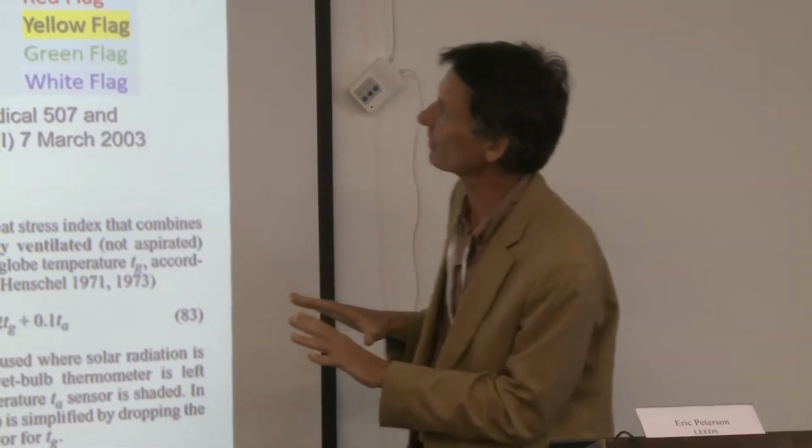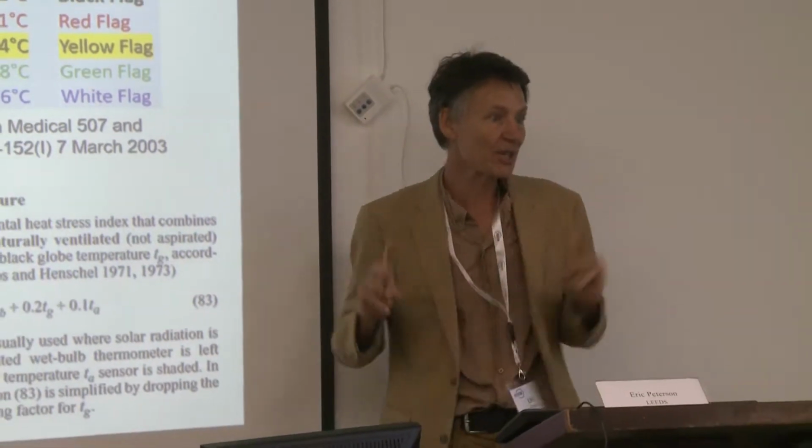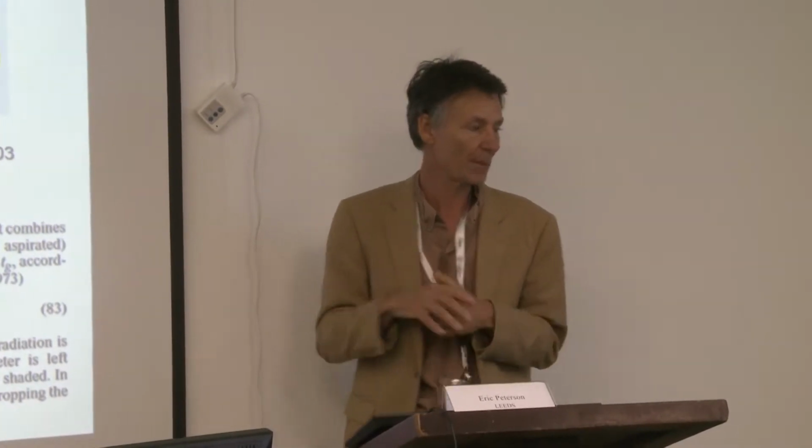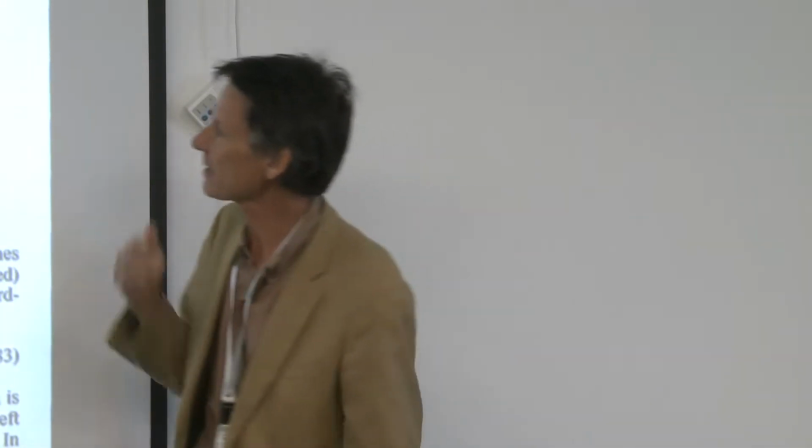Now, the third thing I want to introduce here is the wet bulb globe temperature in the shade. I didn't have room in the paper to talk about this, but I'm quite passionate about it. I think of the wet bulb globe temperature in the shade, that's without actual radiant sources, assuming a really well-shaded place. Think of a tree, a really nice shade tree, and whether you're comfortable or uncomfortable, whether you're stressed in those conditions. To me, a really good passive architectural design ought to try to approach the tree. The shade tree is about the best you could hope for, with taking away all internal loads and having really effective ventilation. That's the best you can do.